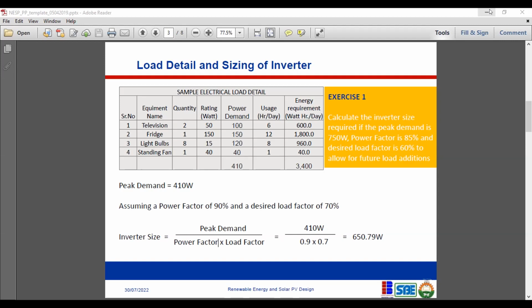Okay, class, as he's waiting, I would like one of the participants to explain how to test for power factor. Give us a highlight on determining the power factor with clamp-on meters. Clamp-on meters that have that configuration inside the meter, you just switch to that and then clamp on. It will give you the power factor reading.